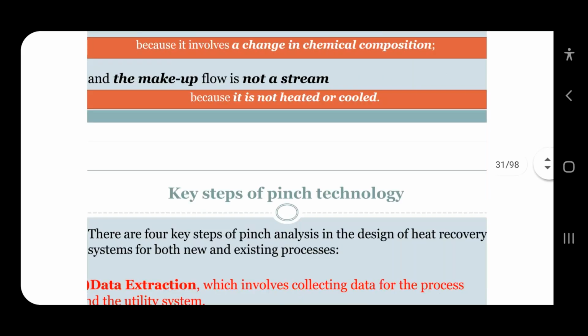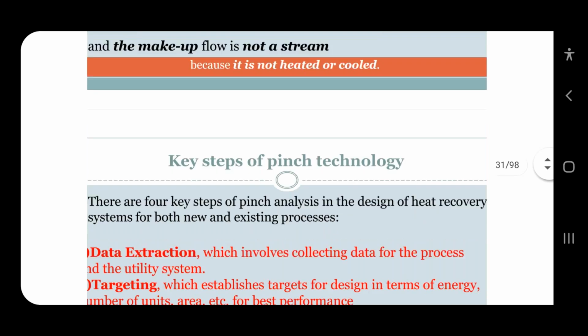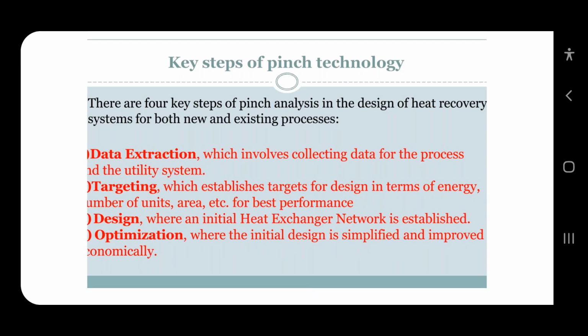Now come to the key steps of pinch technology. There are 4 points. First is the data extraction. We already know the data extraction. It's a simple phenomenon. I will tell you how to extract the values, how to define the flow sheet, and how to calculate or estimate the data extraction points. You have to estimate or measure the temperatures, compute them, and separate out the temperatures.